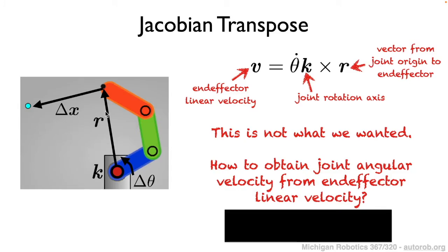So in other words, what we really want is to say, well, we know what the linear displacement is, what angular velocity will align with that displacement. Instead, what this equation says is if we have some known angular velocity, we can calculate what the induced displacement is, which is not necessarily going to be the displacement that we're desiring for our inverse kinematics setup.